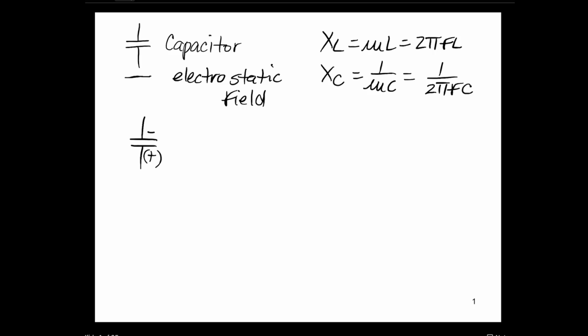In the same way, as we're looking at a capacitor and its voltage current relationship, remember, for an inductor we had the acronym ELI, right? That meant that current lagged the applied voltage. So if we use voltage as the reference, current is lagging. I think you can imagine, if capacitance is the opposite, what would that mean?